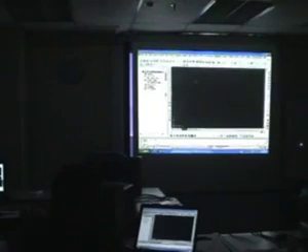Now I've opened up Land Desktop. As you can see, for those who are familiar with AutoCAD, it looks exactly like AutoCAD. You can do anything you want, like draw lines and all that. But this is a new workspace on the left side. AutoCAD does not have this. This is a map feature actually, and we're going to use a little bit of this. I'll show you later. Okay, first I'm going to create a project from scratch for Autodesk Land Desktop.